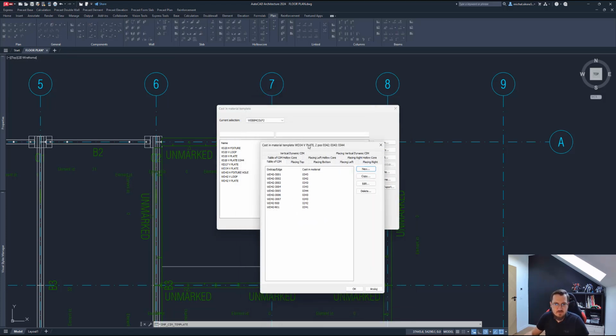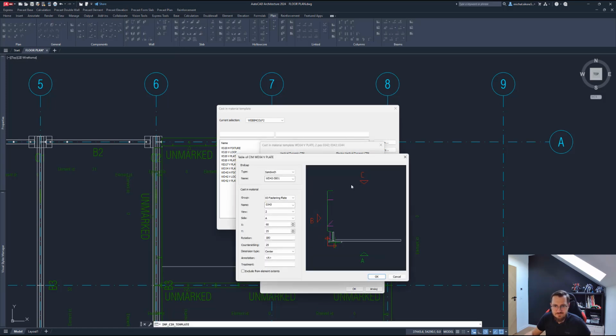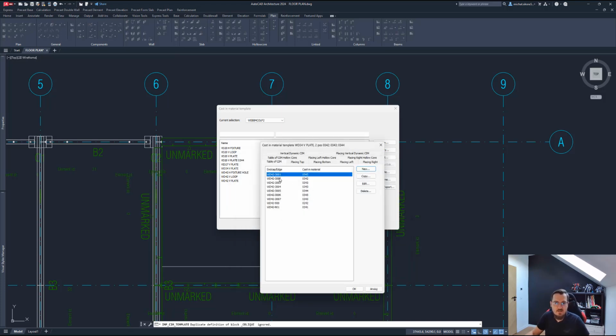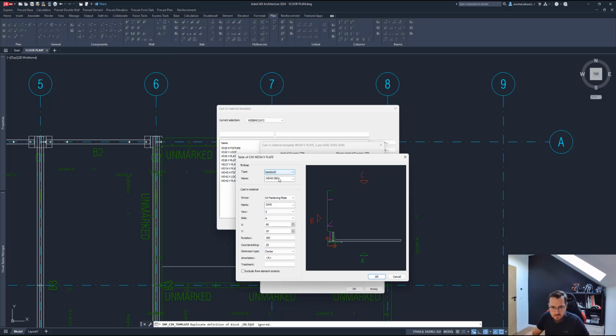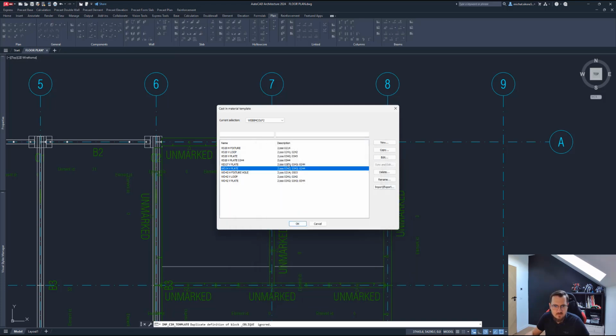And what the casting templates do basically is they look at the end cap that is actually used as a connecting end cap for the element, and then apply a casting material at a specific location, as is the case here. I can edit that, like move the casting material here, for example. As you can see, I'm moving the casting material in this particular wall. Let's go back to 60 as it was before, and let's accept that. And it looks for this casting material, which I now just realized is a wrong end cap for me to edit. That might be problematic for this particular one.